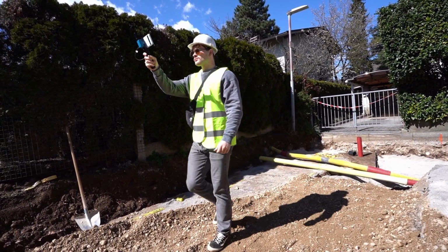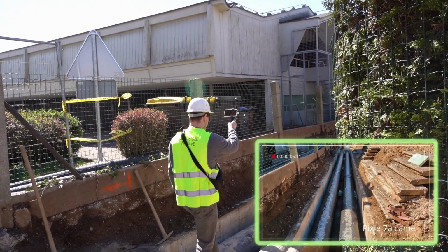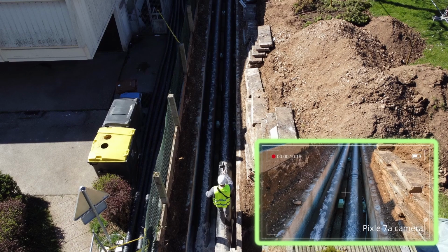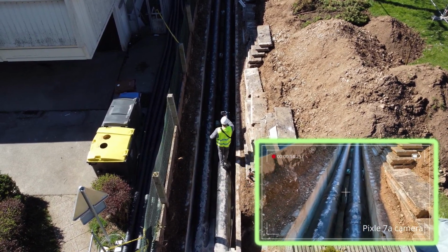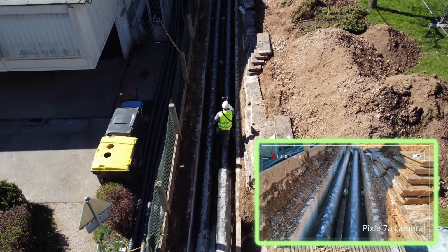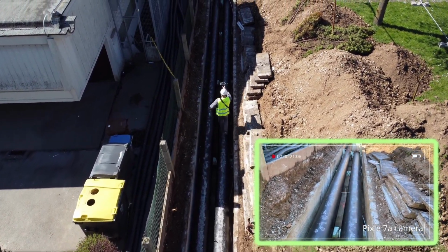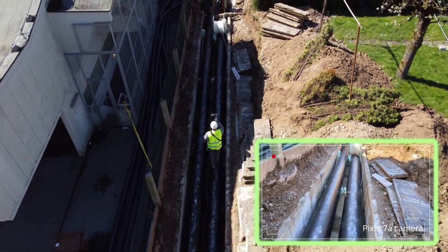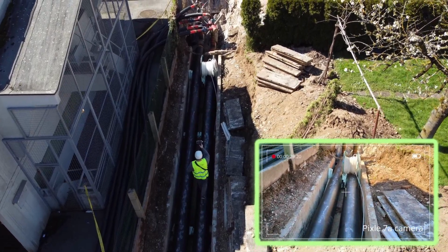It is important to walk slowly, as we get telemetry data only twice a second, so a fast pace might reduce the accuracy of our result. It is also important to keep an equal distance from the filmed object throughout the whole video. Avoid any jerky movements to make the extracted images as clear as possible. Also, keep the important part of the video in the center of the frame, as the edges will not be reconstructed that well.